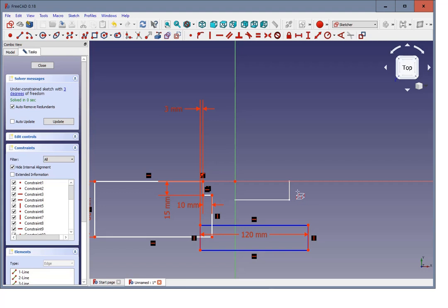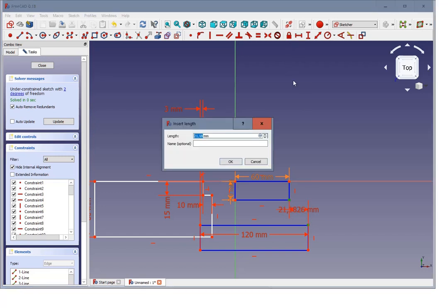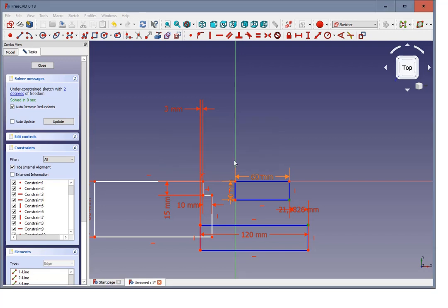And this shows the box sign, and now we can make a carbon copy from the previous sketch of the other body. As we are in construction line mode, it stays in construction mode, and now we can just add a constraint, and that constraint has to be 12 plus, let's say, 15 millimeters.